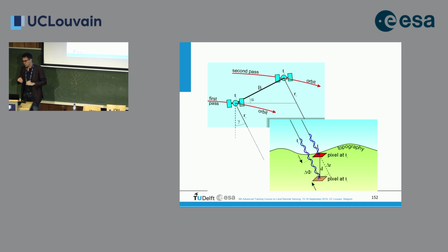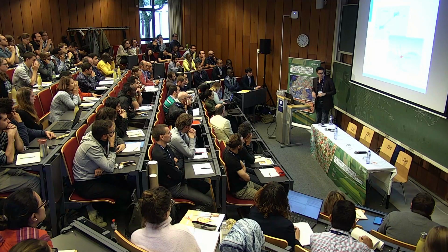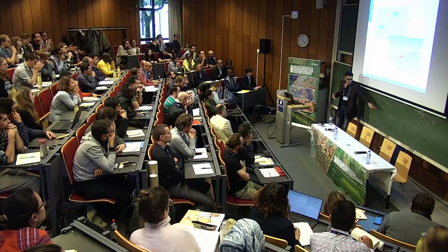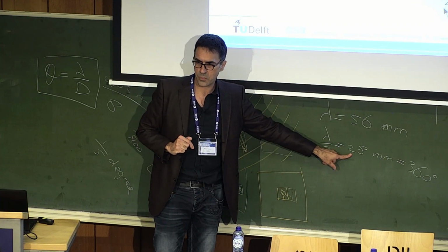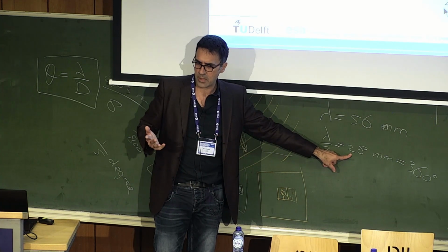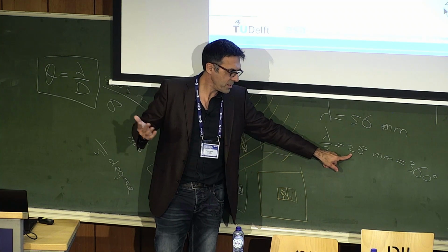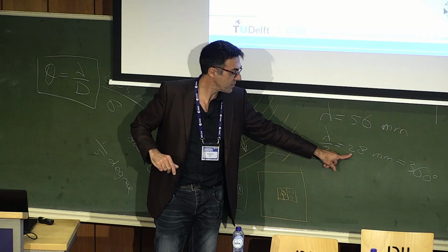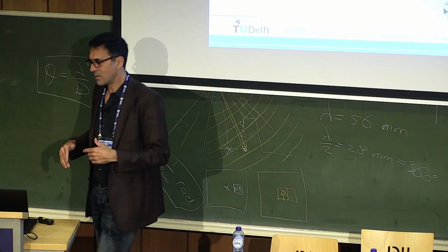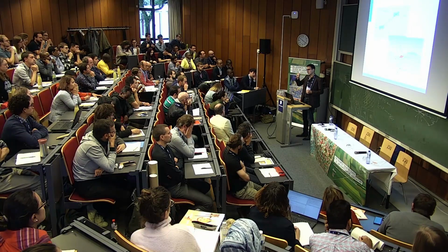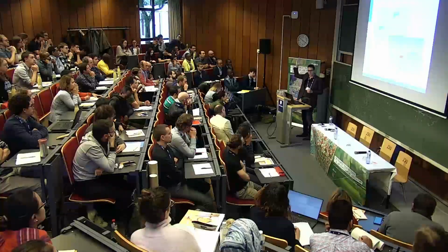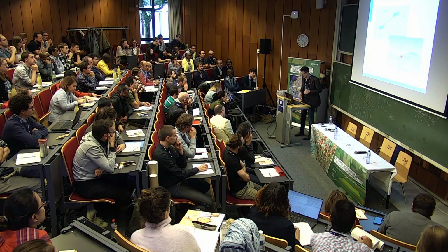If I can measure 1/10 of a cycle, that is then 1/10 of 360 degrees, so 36 degrees, would also be 1/10 of 28 millimeters, would be 2.8 millimeters. Now I can measure maybe 1/20th or so of a cycle. So I'm getting to a precision of measuring less than a millimeter of height change from a satellite which is 700 kilometers away in space, right? So this is a very spectacular thing.